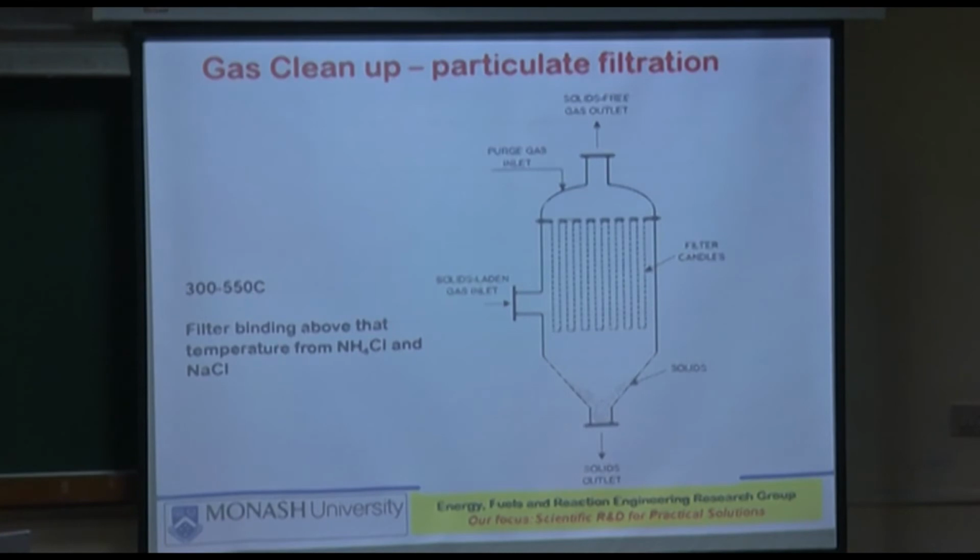How is it done? The frequency of purging and the amount of purging are very critically controlled parameters in a gasification plant. It seems innocuous, but these are extremely experience-driven numbers.